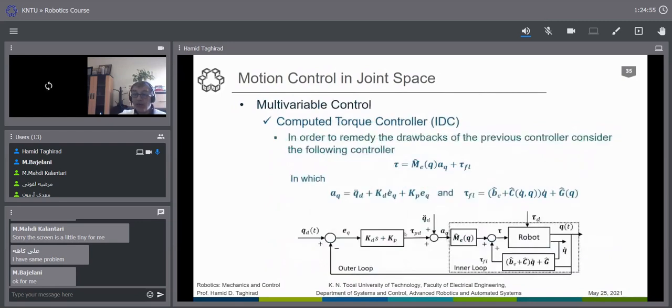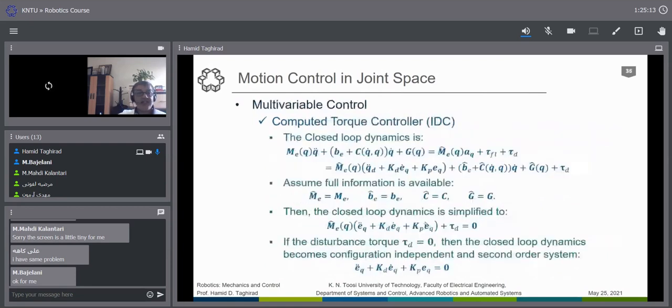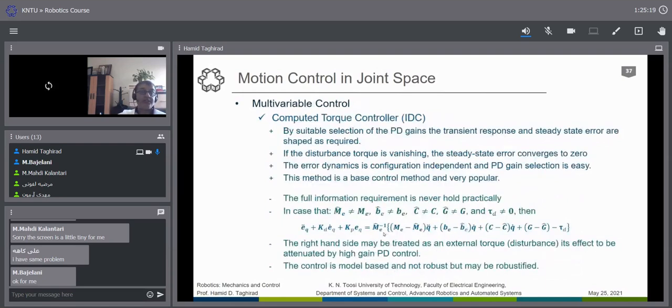As you see, this part becomes much more important, and you should spend a lot of time on accurate tuning of this PD controller, not only to have the tracking error as you require in the second order case, to have zeta and omega designed as you wish, but also to reject the disturbance. And this is the magic of feedback that we are using.